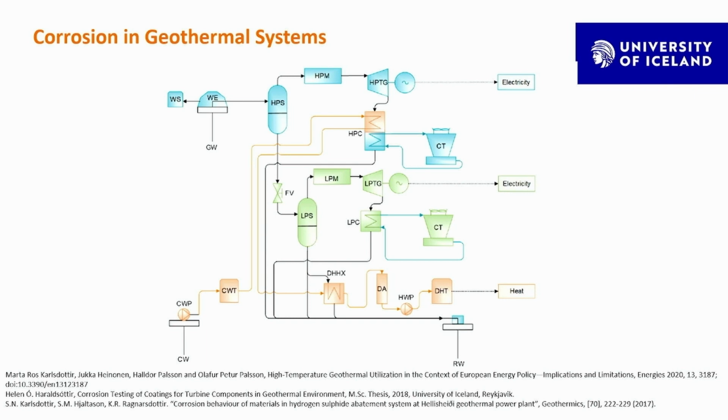And here you see actually a schematic of a power plant, a quite complex power plant representing the Hellisheiði geothermal power plant close to Reykjavik, the capital of Iceland. This is the geothermal well, and then we have high pressure and low pressure separators. We have, of course, the turbine unit here, and then we have heat exchangers, cooling towers, and so on and so on.